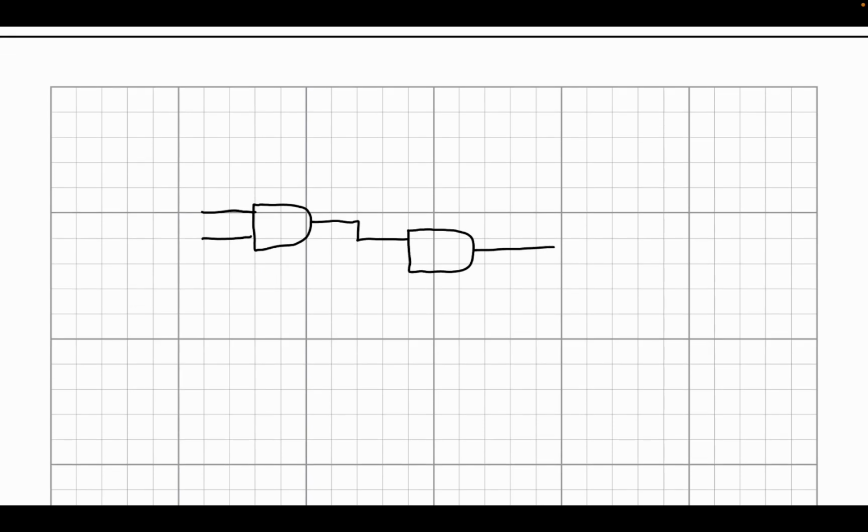So suppose that I've currently got the two inputs of this AND gate at 0 volts, and then I'm going to increase this one to 1.2. And then let's pause time as soon as I put this second input to 1.2 volts. And let's look at what's happening at the output.